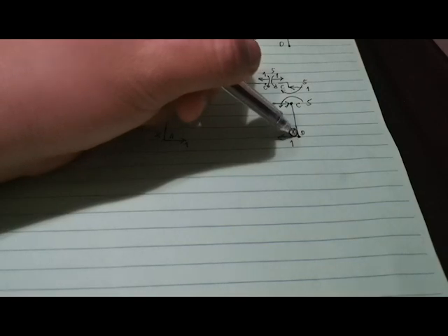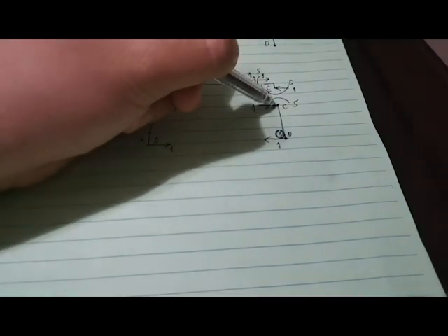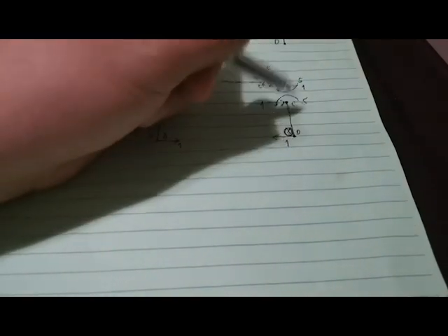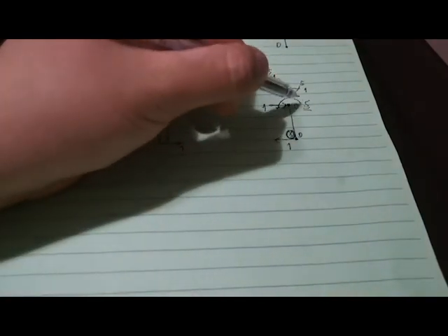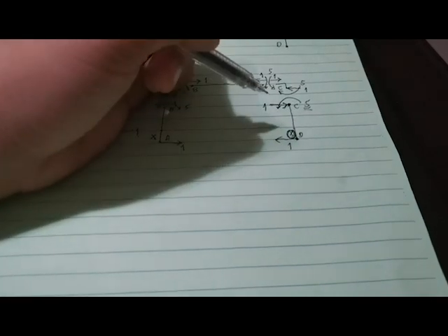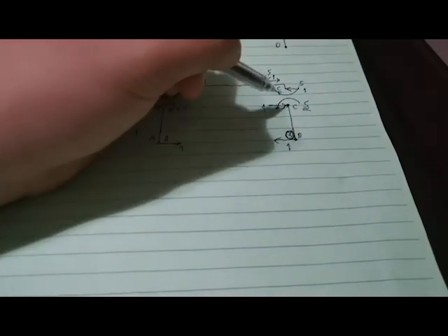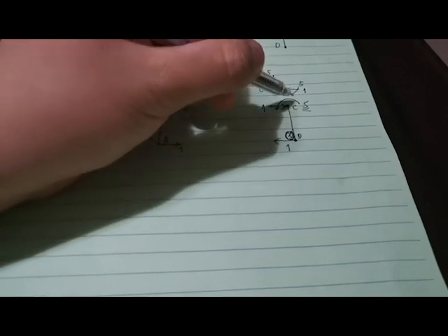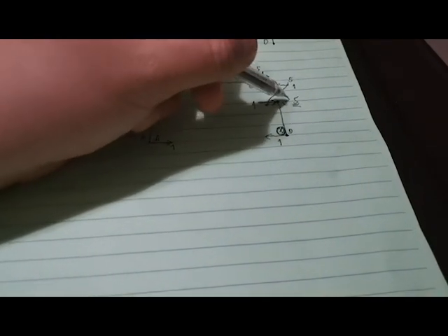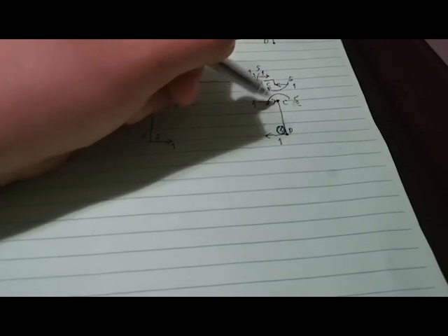And if we multiply this 1 kilonewton unit load by the length, which is equal to 5 meters, we will be able to know that there is also a moment at joint C equal to 5 kilonewton meter. And since this is clockwise, the moment at C just acts in the opposite direction, and this is counterclockwise at C.